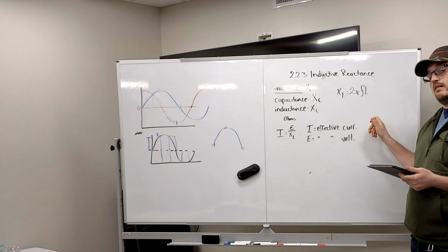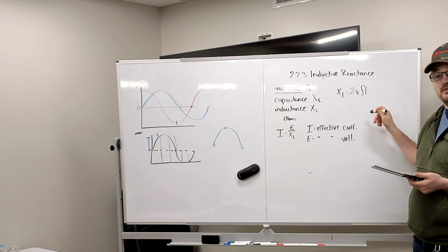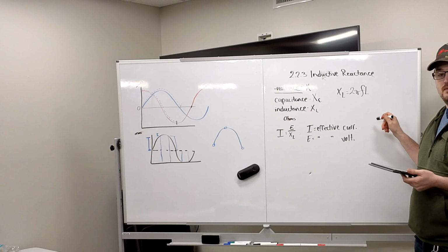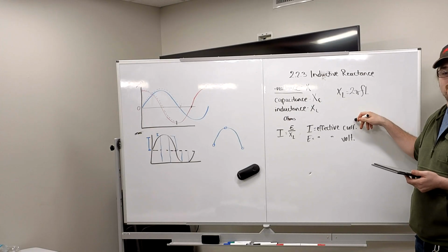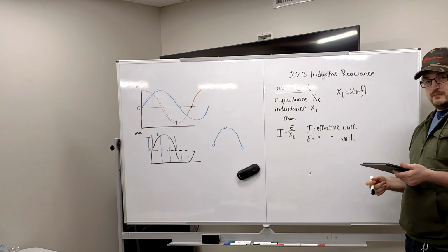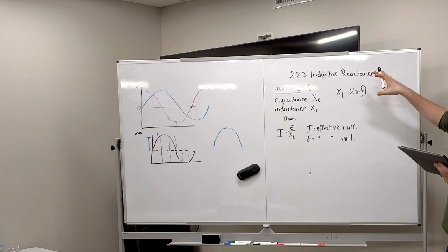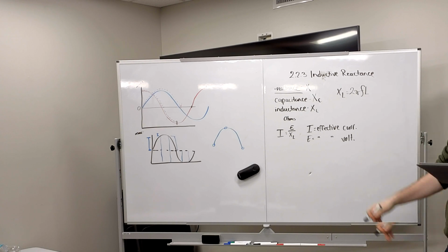Remember when I was explaining RMS voltage to you guys last week, and you asked me what about the rest of it? That's the rest of it. It's used to maintain the inductive field. So, in short, the energy required to build up the field gets put back into the circuit.